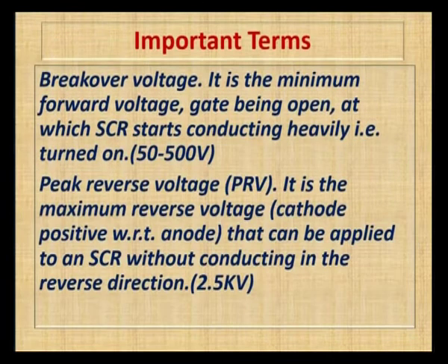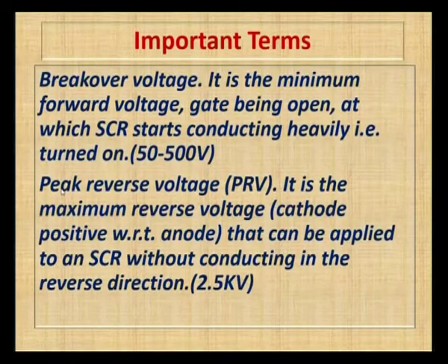Next, some of the important terms we need to know about SCR, which is the breakover voltage. What do you mean by breakover? It is the maximum voltage at which the SCR will conduct heavily when the gate is open. Above this the SCR will conduct heavily, and below this it won't conduct. Example, if the breakover voltage is 200 volts, it means the SCR won't conduct below 200 volts, and when it reaches 200 volts it starts conducting heavily.